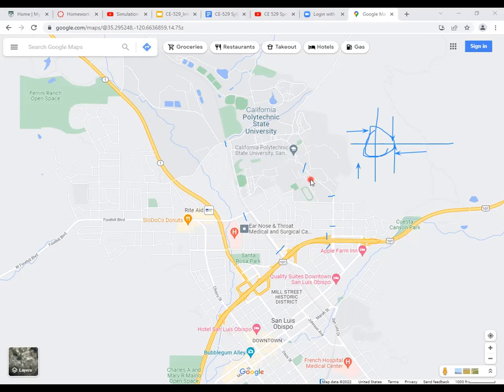And this is all context dependent, by the way. Why is it context dependent? Think about this. If you're talking about morning peak hour, your big origin would be maybe the freeway exit, maybe where people come into the campus from. So those would be your big origins, right? The big origins might be the intersection near this Highland Drive intersection, maybe over here. So you need to know that. The traffic coming in from here, probably need some traffic coming in from here.